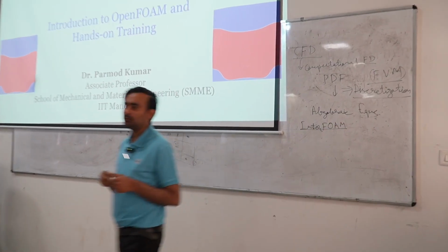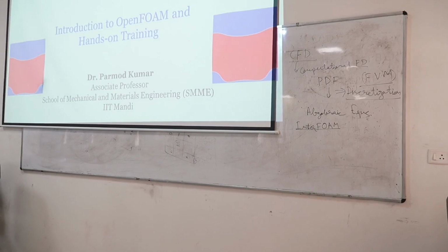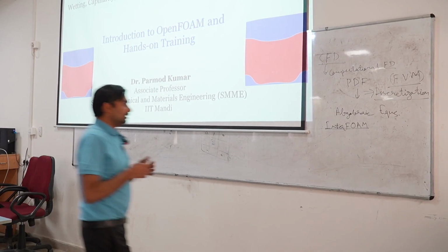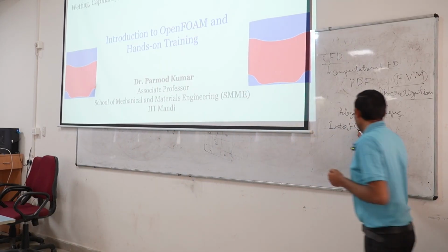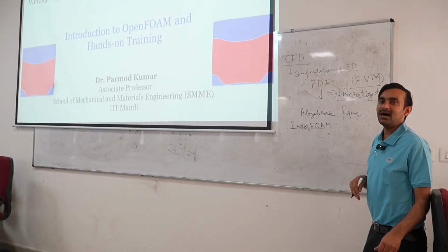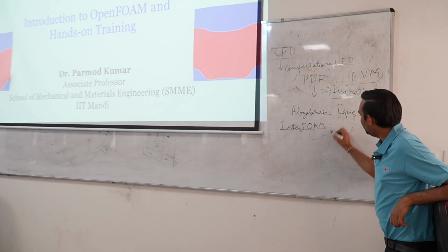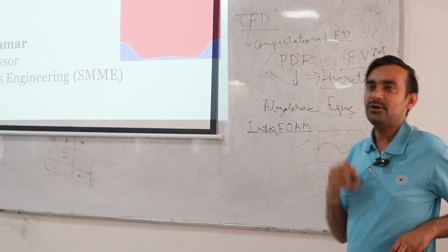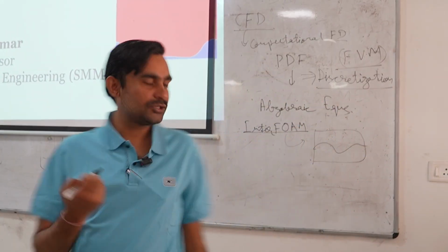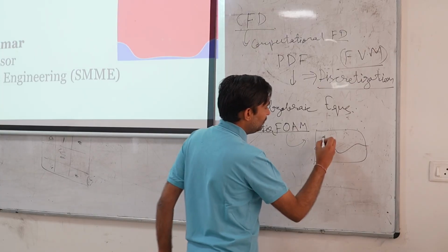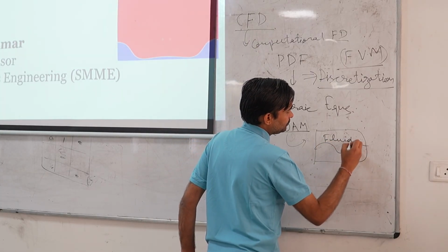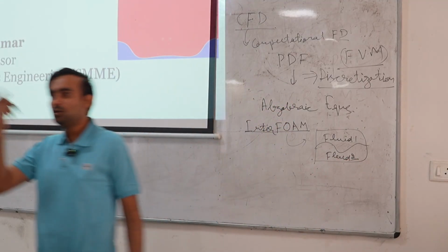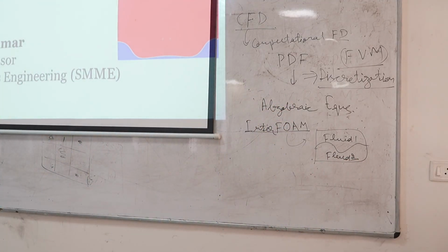So, interFoam is the solver which we will try to practice in this hands-on session. This interFoam solver allows us to simultaneously study the behavior of a system which contains two fluids. So, for example, if I have fluid 1, this is my fluid 2. Now, there can be two types of occurrences in these two fluids.